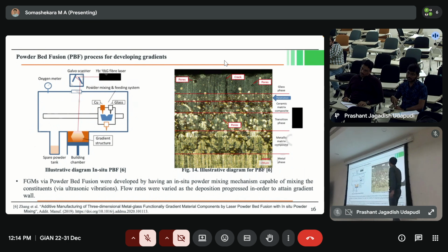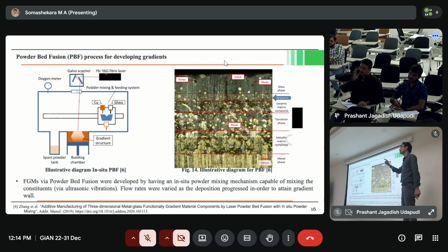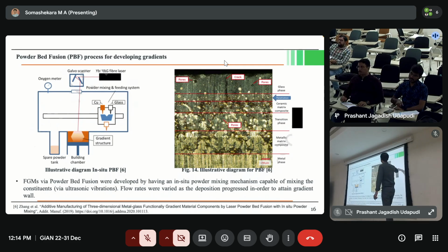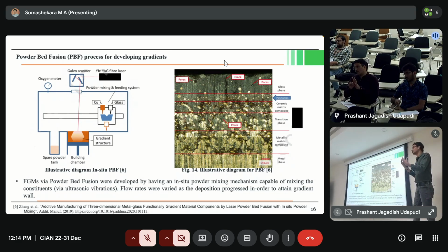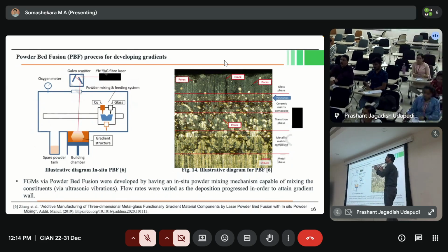You can see how bad the structure formation is here, right? They don't go well together because their composition is completely different. When the composition is completely different, the melting also varies. For example, the melting temperature for material A may be different compared to material B, right? Now you try to join and mix them together, and then you give the same power.